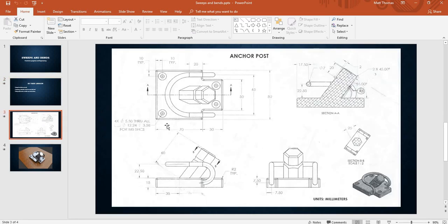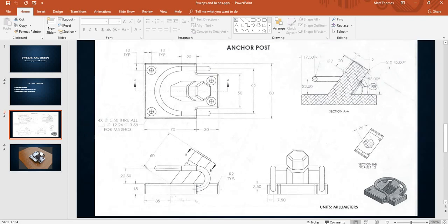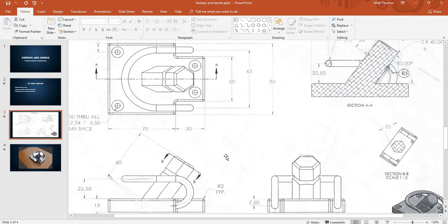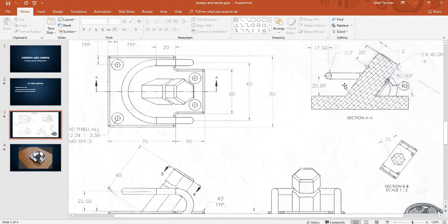So anyway, we're not going to be using any of the cutting tools today. We're just going to be using the follow me tool and the union tool. So first let's see if we can find the dimensions that we need. We know from center point to here is 22.5 millimeters. The diameter needs to be 7 millimeters, and we're sitting 17.50 to that center dot.